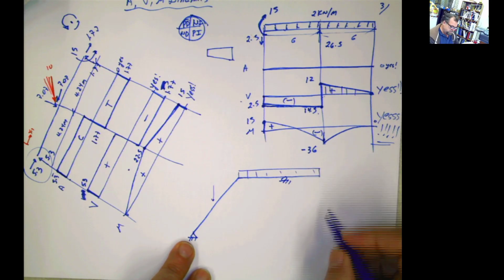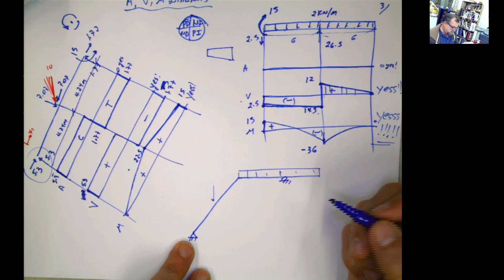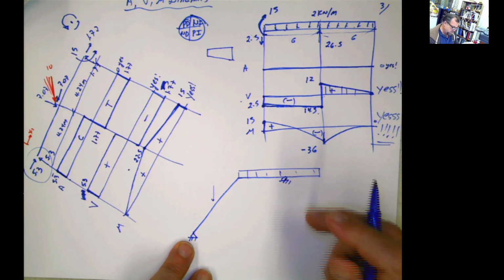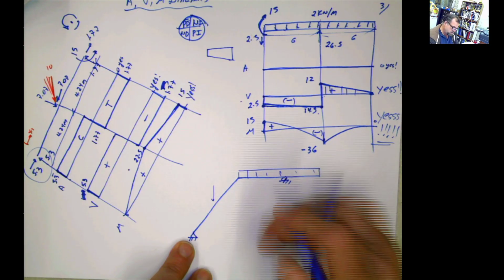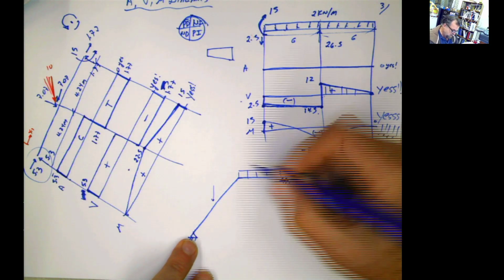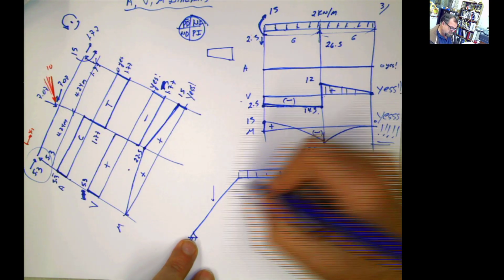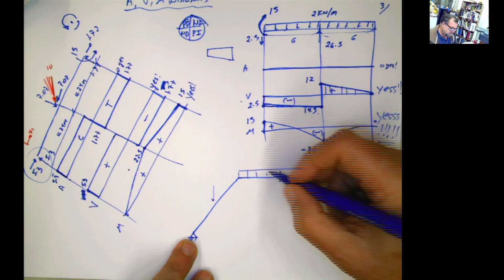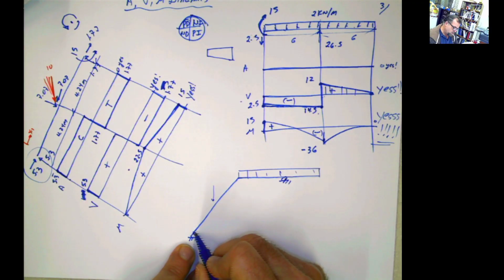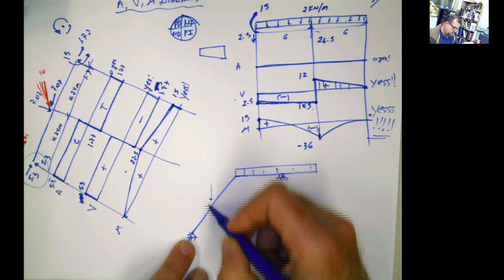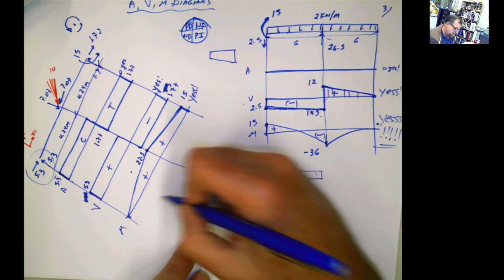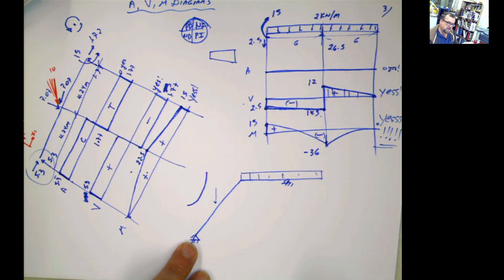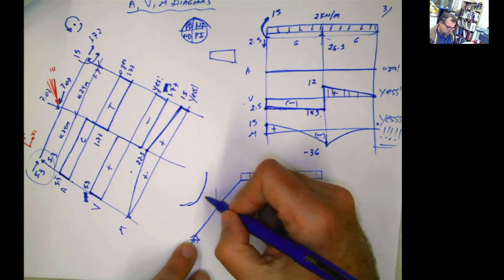Now look at the moments. What is first? This is a roller, right? So this structure, because of these loads, might displace to the right. I don't think so. Everything is symmetric. I don't think it's going to displace to the right. However, this is a pin support. This is going to suffer a rotation in either direction, but it's going to be a rotation. And if you look at the moment diagram, it's positive. That means that for this whole area, the shape has to be like that, a frowny face. Compression on the top, tension in the bottom.